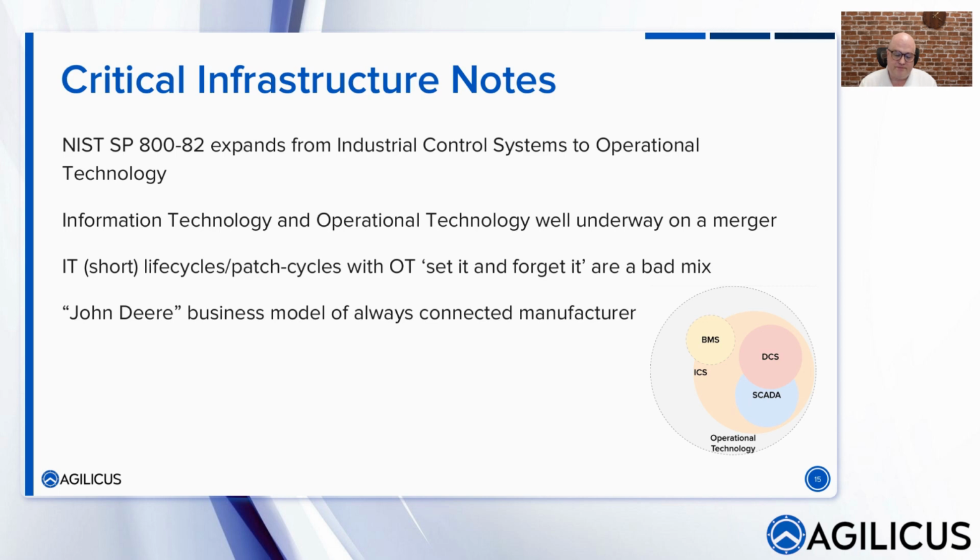Operational technology is around more of a set it and forget it type environment. I'm going to bolt this pedestal onto this concrete, and I'm going to put this thing in place, and in 20 years I'm going to come back and change it. Those two are colliding. That HMI, that human-machine interface on that pedestal, is now running an embedded version of the same thing in the left column, and it's Windows 7 or Windows XP, and it's not patched because there are no patches, and it originally thought of itself as running in a very trusting universe where the only people that could touch me were physically adjacent, there's access controls to the room, and suddenly they realize that it's not that safe.